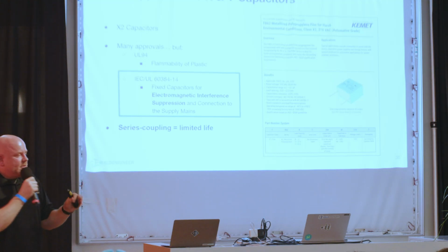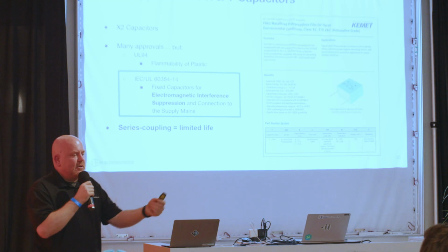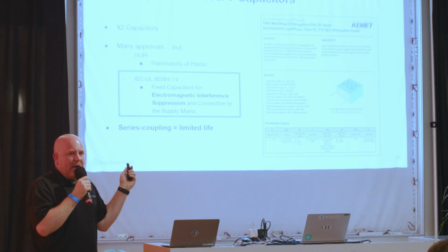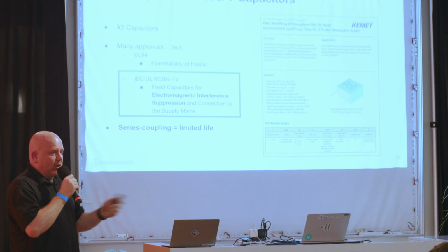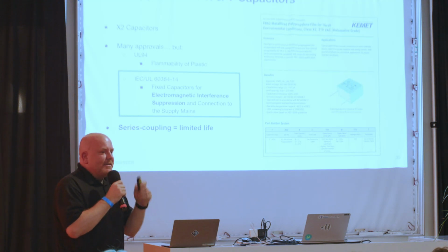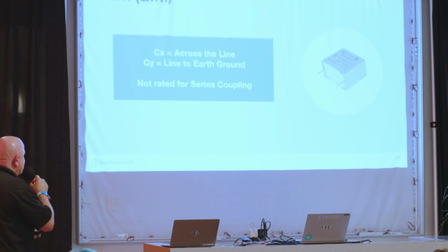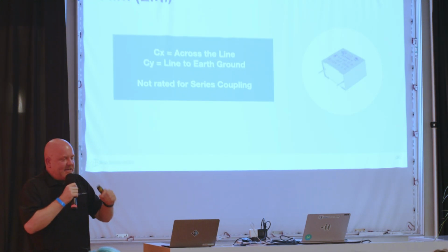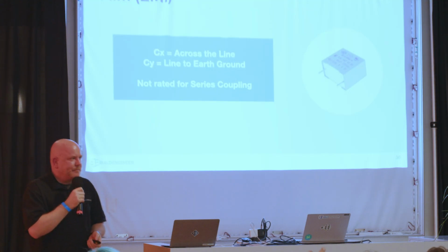Also, and this is actually intentional, these capacitors are connected to line and typically also to something metal in the design. They are designed to wear out very quickly. And if you use them as a series dropper where you're putting a boatload of current through them, they'll wear out in 2 to 3 years. They are not designed to carry a heavy load. They're meant to be EMI suppressors. So all I'm going to say there is for film caps, look at the data sheet and see what application it's meant for, because there's a reason they're saying certain applications.